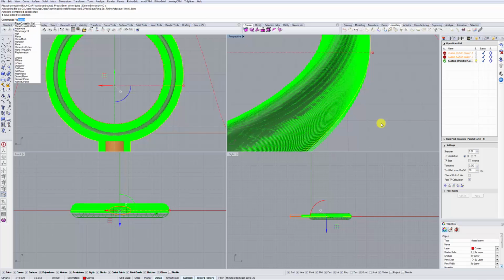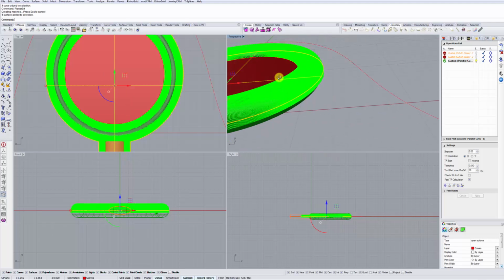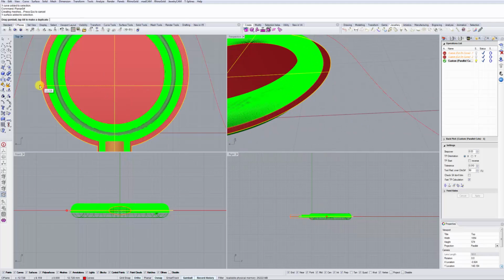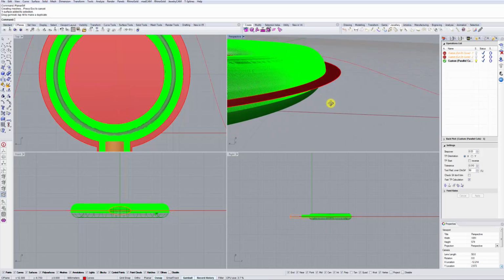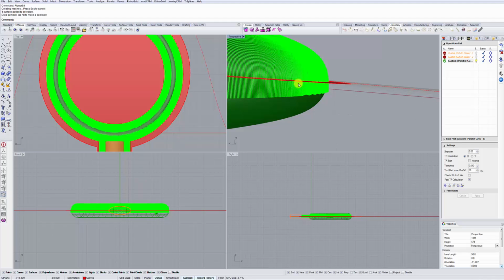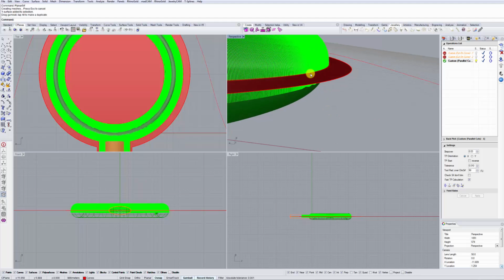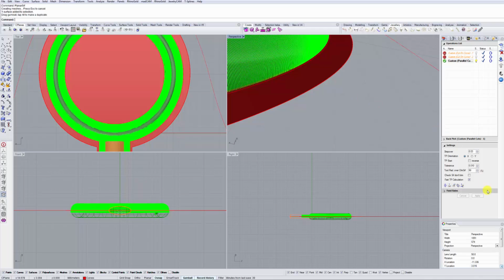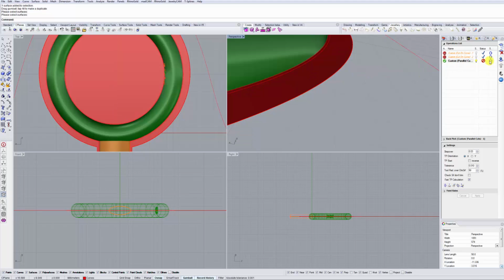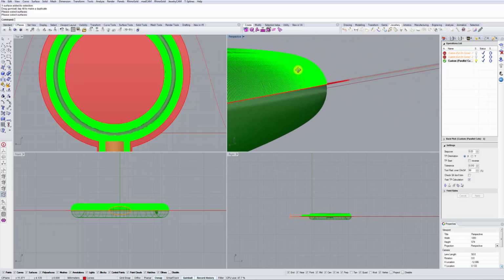So a simple planar surface command in Rhino will do that. Let's say we create this big flat surface here, and you'll see at the current moment we're waterfalling beyond it. But let's say we want to always stop right at this point. What we do in our settings is click this last button, set additional check surfaces, and click on the surface and press enter. Now, when we recalculate, you will notice that the toolpaths will no longer go beyond this point. This is very useful when you have holes or other areas where you want the milling to stop.